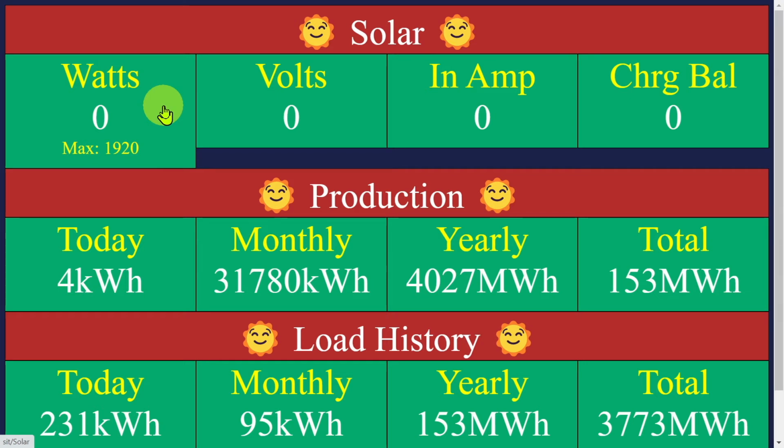This is calculated by multiplying battery volts with the max PV charging amperes of the inverter. I have a 3 kVA inverter, but the max solar production I noticed was 1980 watts. I have over 2.6 kVA panels installed. Right now there is no solar voltage. Interestingly, on moon nights I can see some volts. With white clouds, city lights produce some volts too.